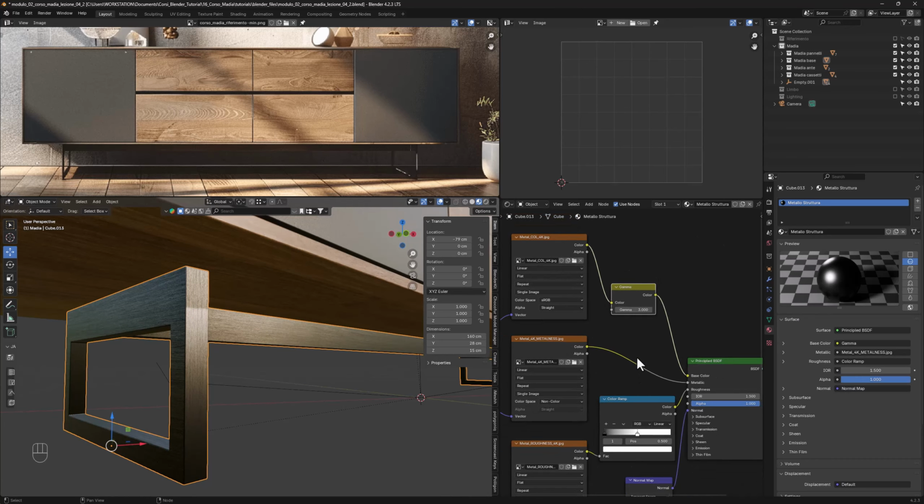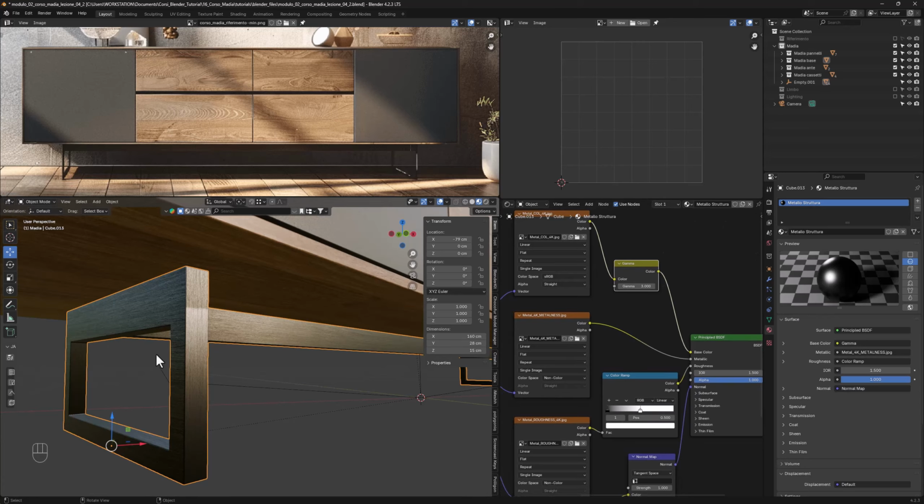There's still something to fix. If we carefully examine the front profile of the 2 shoulders, we can see that the texture is applied vertically. However, to maintain a consistent and realistic appearance, it would be more appropriate to reorient it horizontally. In fact, metal profiles generally retain the same brushing direction throughout their length, so it's essential to adjust the direction of the textures to reflect this characteristic.